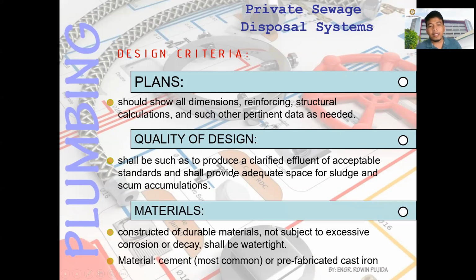Then the materials: constructed of durable materials, not subject to excessive corrosion or decay, and shall be watertight. The most common materials are cement, concrete, or prefabricated cast iron.